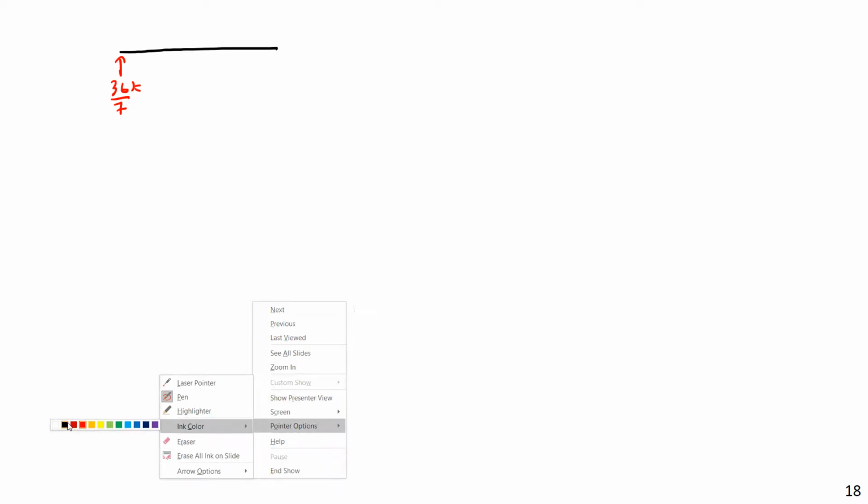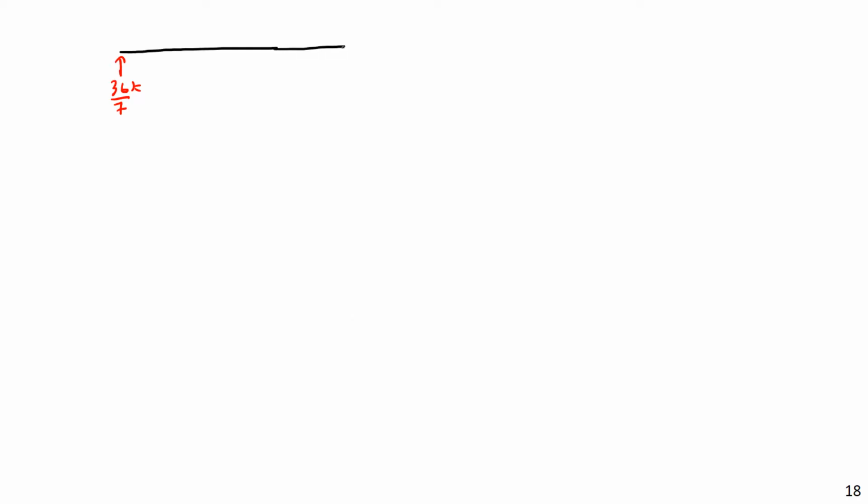So let me go ahead and redraw this free body diagram over here. On support A, I have a reaction of 36/7 kips. Maybe I'll make this a bit longer. And then at B, I have a reaction of 27/7 kips. And then in the middle, I have my triangular load, triangular downward. The dimensions are 4 feet, 6 feet, and 4 feet.